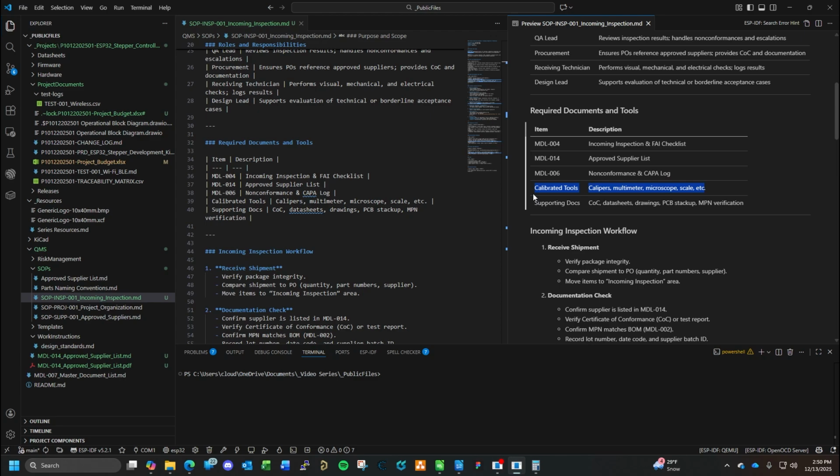If they are used in final testing before you package up the product and ship it to a customer, that power supply and digital multimeter now have to be calibrated. And you have to have traceability for it. You have to have artifacts, and it's typically a NIST traceable certification. There are companies that specialize in calibration, and it's not cheap. Again, welcome to another expense.